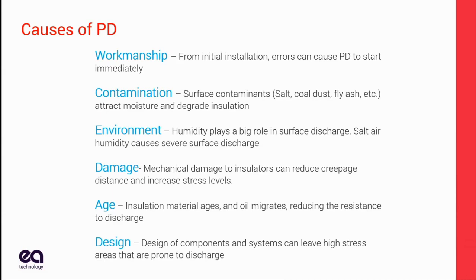Contamination. If you are anywhere near the ocean, salt air, salt humidity. The islands in the Caribbean and Bermuda, they all suffer terribly from salt air and humidity, and that causes a lot of problems. If you have pollution from your facility, if you're an oil refinery or that, even though your pollutants or contaminants may not be conductive, they attract and hold humidity. They hold moisture, and that moisture makes the surface conductive, which then changes the field strength, which can then cause PD. Damage, of course, anything that's going to damage the insulation can cause it.